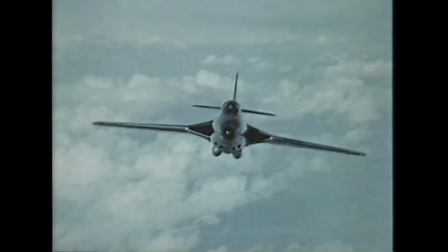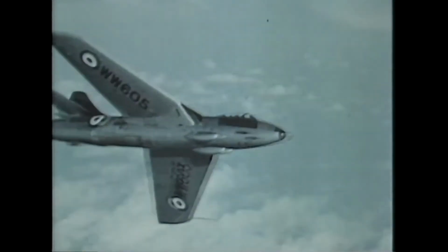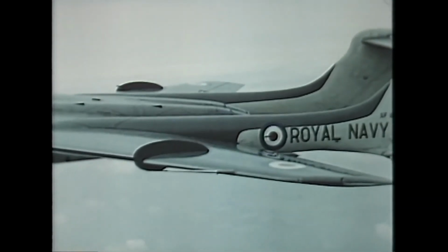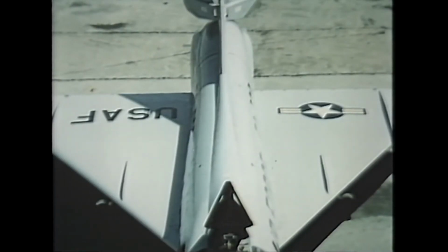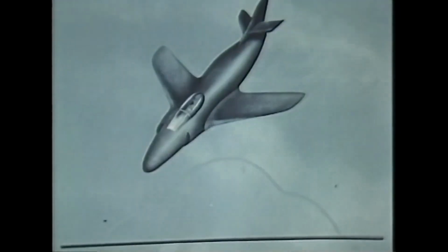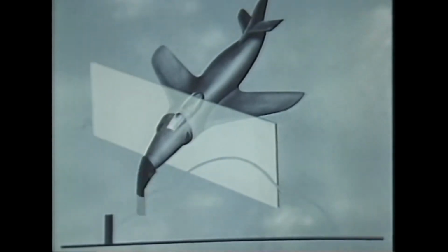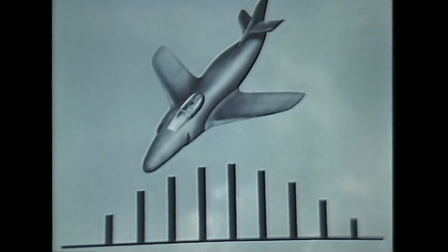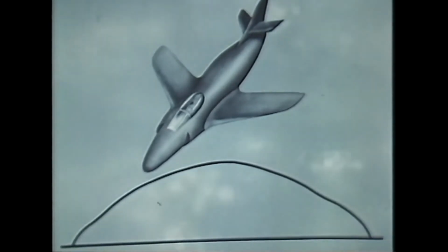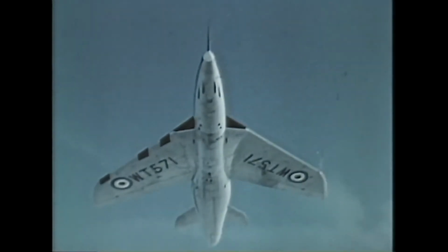For transonic flight, thin wings and sweepback are again used. For, by lowering the speed of the air as it passes over the wing, they reduce the severity of the shock waves. Compare the behavior of thicker and thinner wings in the wind tunnel at the same speeds. Streamlining an aircraft's cross-section helps to reduce the huge increase in drag. The aircraft's shape is modified so that the cross-section area pushing through the air changes smoothly from nose to tail. This usually means giving the fuselage a waist to compensate for the wings and flaring it out again behind.